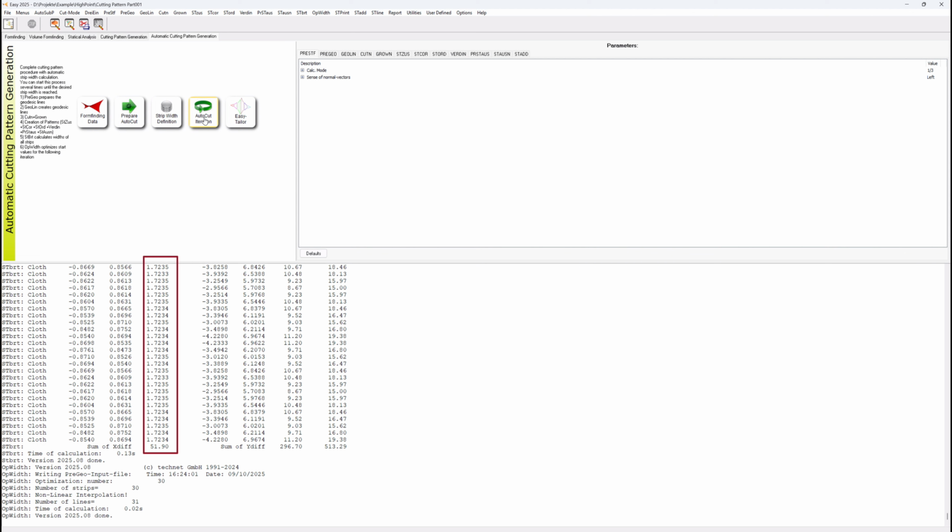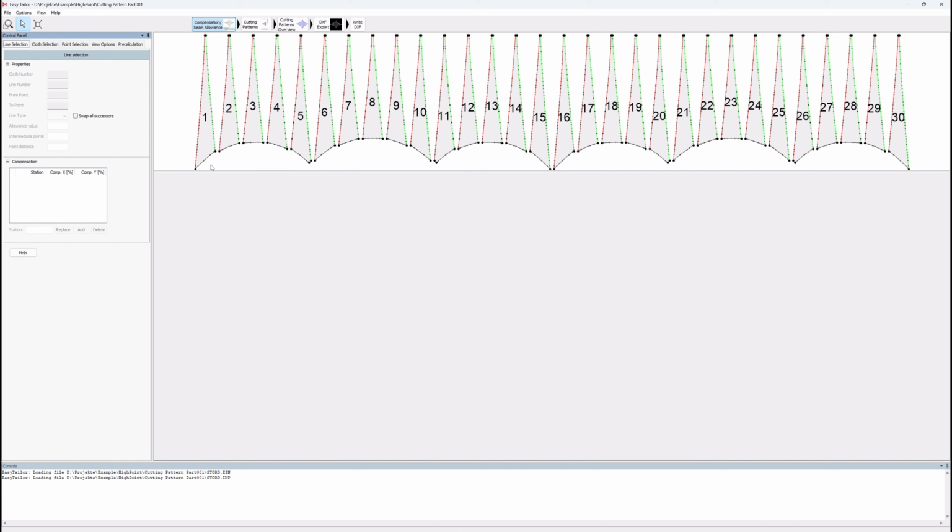for our cutting pattern. We can now display the flattened cutting patterns graphically and adjust additional tasks and properties for the final layout. This is done by clicking the last tile, Easy Tailor. As before, the program opens in a separate window. It now becomes clear that the elements have been realigned in the warp and weft directions, perfectly matching the requirements of the fiber orientations. The uniformity of the cutting elements is also clearly visible.